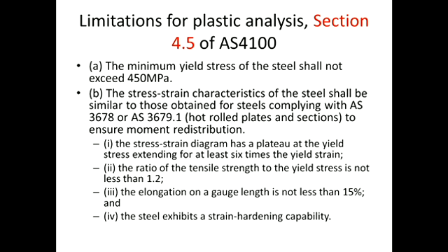So the ratio of the tensile strength to the yield stress. From what we discussed last week, what would this be indicating to us? If you have a much higher value of the tensile strength compared to the yield value, in terms of the behavior of the stress strain curve, maybe this is indicating the strain hardening effects within the material.